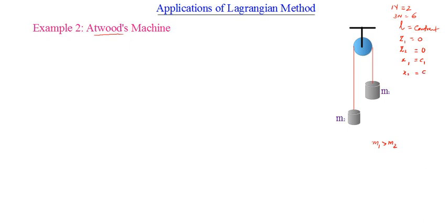So can you see how many equations I have which represent constraints? L equal to a constant, so altogether I have 5 constraint equations. So I can say here k, the number of holonomic constraints, is equal to 5. So what will be the number of degrees of freedom after all these things? It will be 3n minus k. This is a standard procedure, and only to make you familiar with it I am giving you this one. So it will be 6 minus 5, which is equal to 1.